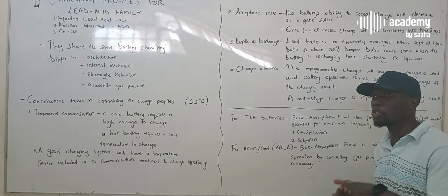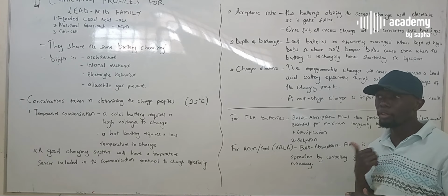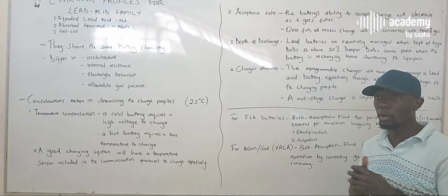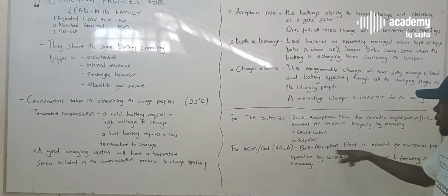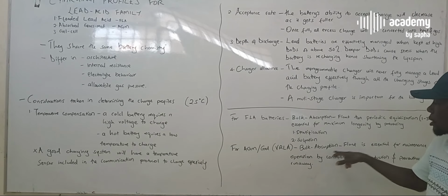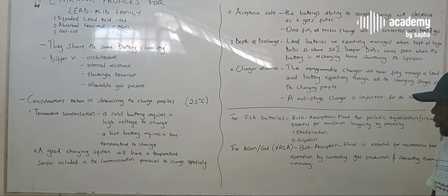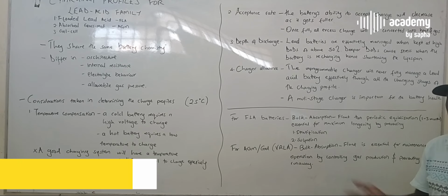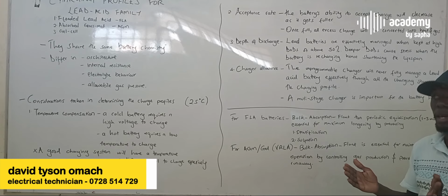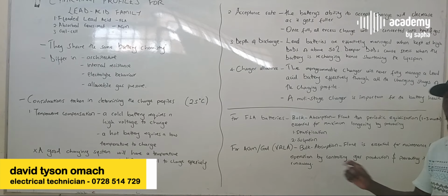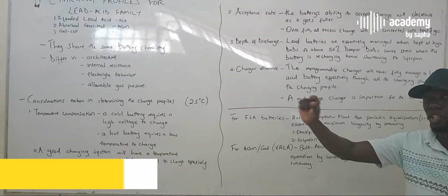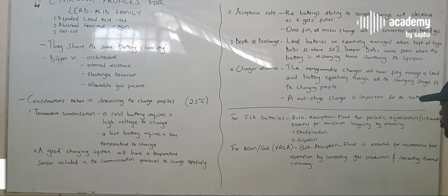If you link it to a good charge controller that allows you to program so that it goes through all these stages continuously, you are good. But if you link it to a charge controller that does not have these, then it lowers the actual lifespan of the battery, because it will keep that battery in one charging stage for its entire lifespan.